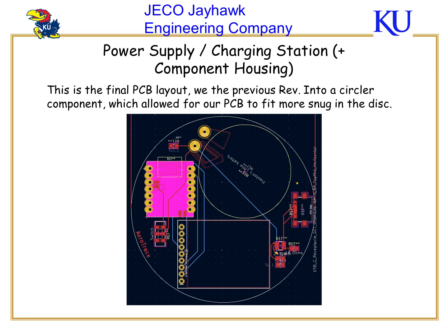This is in the threshold to charge the battery, so we felt like this was okay, even though it was a little under what the proper charging current was supposed to be. The output of the charging controller was put into the positive terminal for the battery, where the positive terminal contains a trace that goes to an on-off switch.